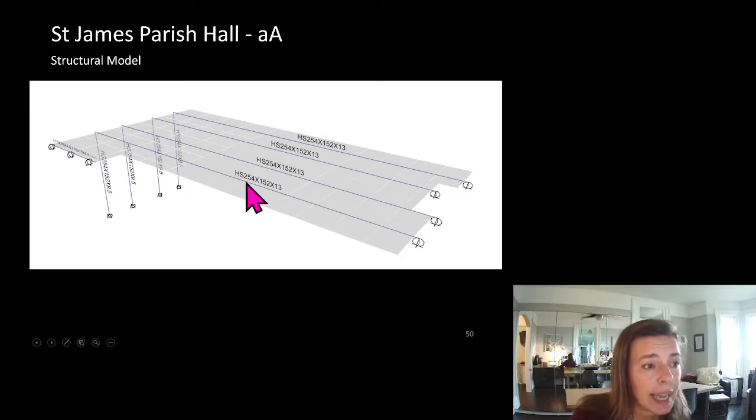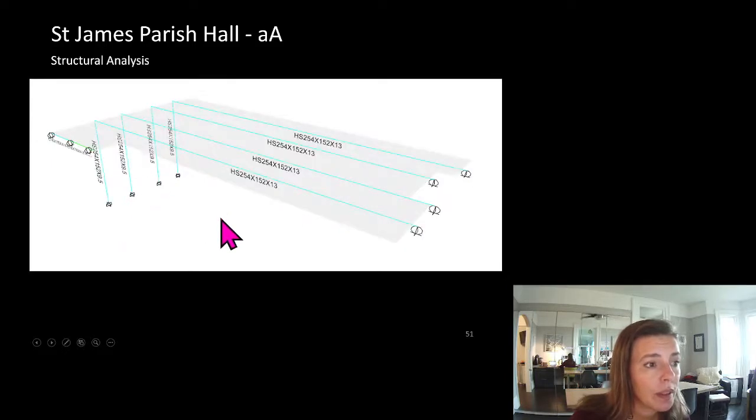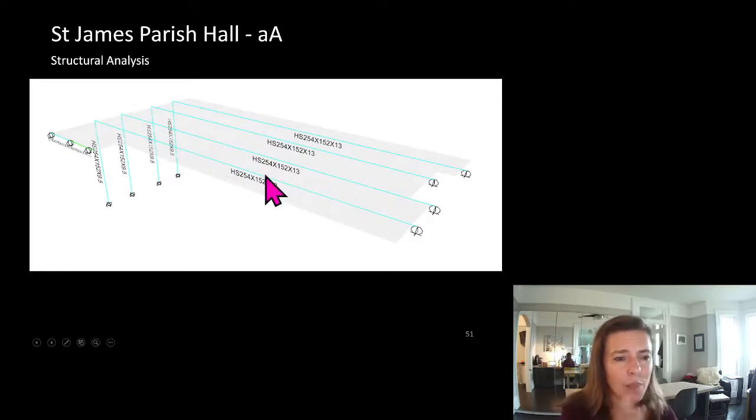So here is the actual structural analysis. We had 10-inch by 6-inch HSS elements making up this structure. It all worked easily. Look how easily those worked. If you see something like this where everything is blue, at least in my structural analysis software, this means that they're all at less than 50% capacity. What do you think is governing this design? If they're all at less than 50% capacity, I guarantee you deflection is what's governing this.